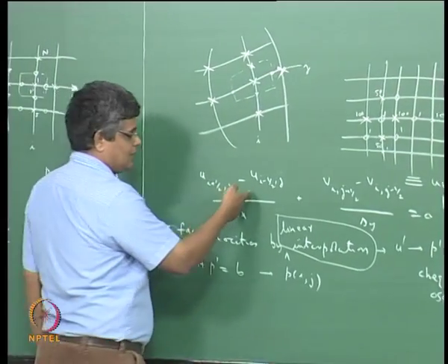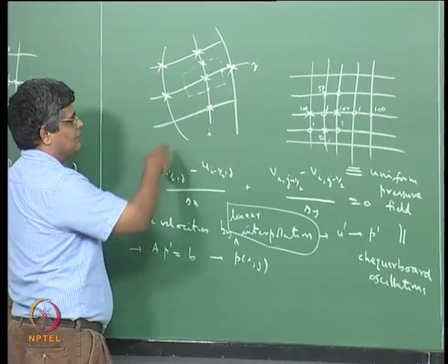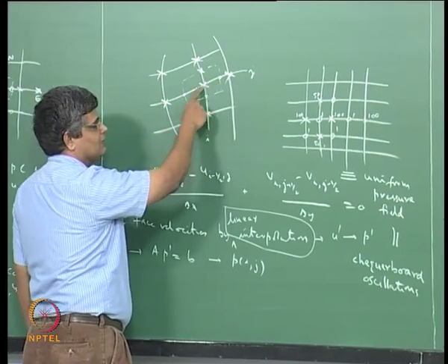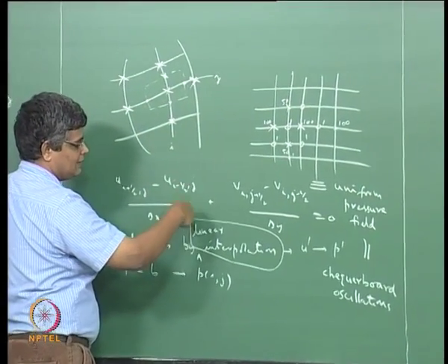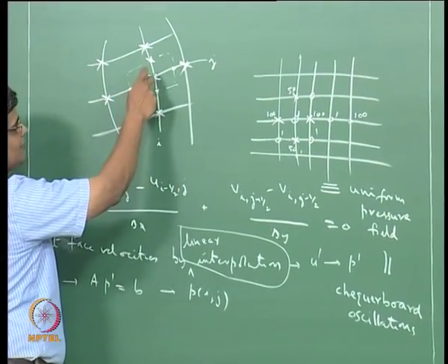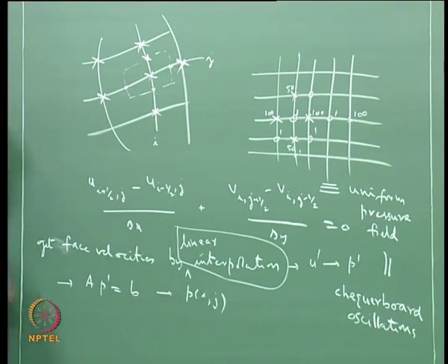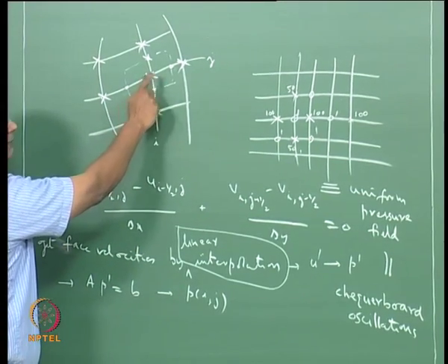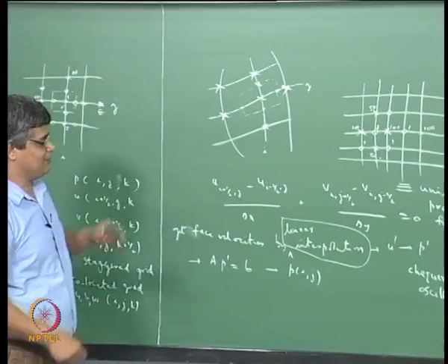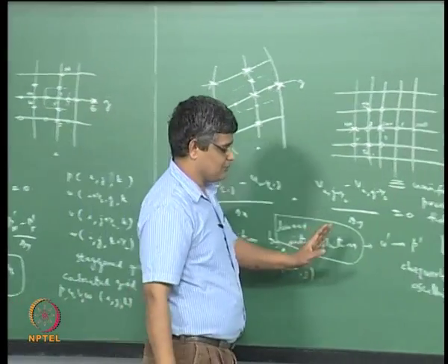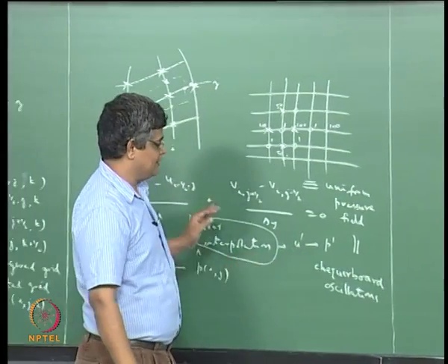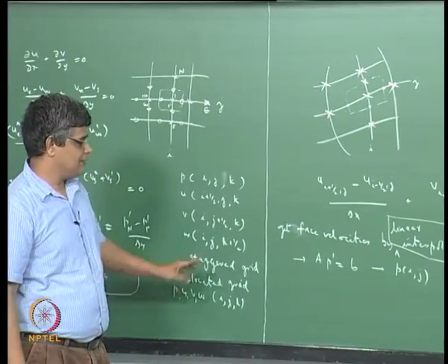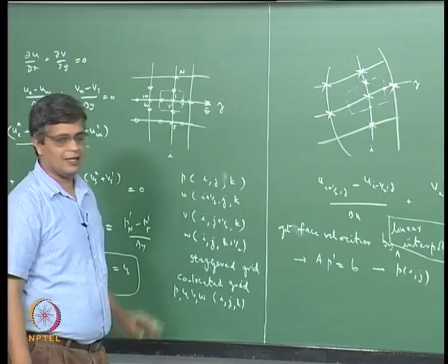When we want to discretize the continuity equation at the center of the cell, we need the phase velocities, and these phase velocities are obtained from the discretization of the momentum equation at about the same point. Therefore effectively the pressure evaluation at a particular point gets decoupled from the velocity equation at that particular point, and this gives rise to the checkerboard oscillations. This is a well known problem with the solution on the collocated grid, and this can be readily avoided by using a staggered grid approach.